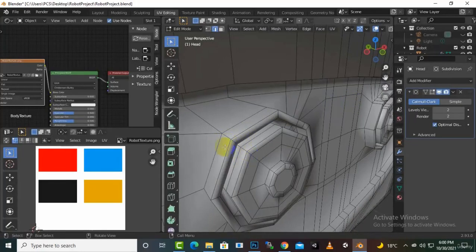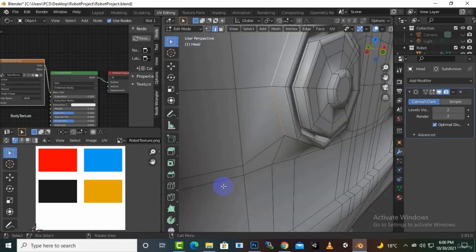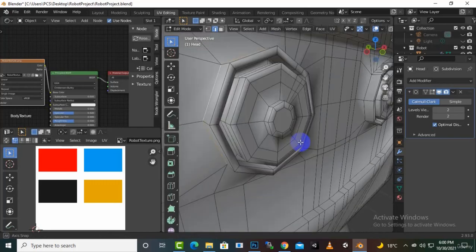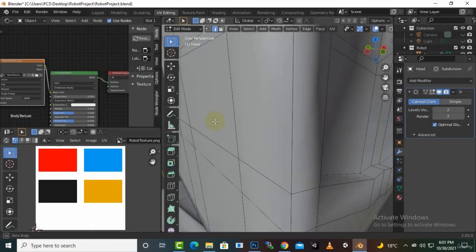Anyhow, we will select this eye section. So let's select this loop, and you can see that for this loop we can select it with shift alt click like this, and like this, and then we have to select it entirely. But if we want to select the area from entirely of only one loop, then we can create another loop here.